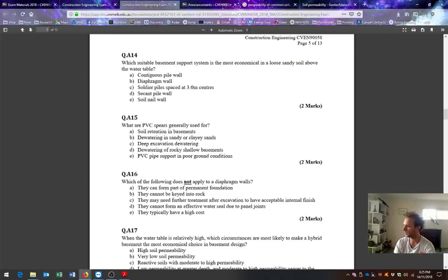Also, is only hard pile or soft pile can be keyed in? No, we can key in the soft pile. The soft pile is only soft because of what we're filling the pile with. If we fill it with a soft, weak concrete, no reinforcement, it's a soft pile. We can still construct it via boring into the rock. So no, we can get both piles socketed into the rock. We might go a bit deep with the hard pile to get more capacity, but technically you could socket both in.